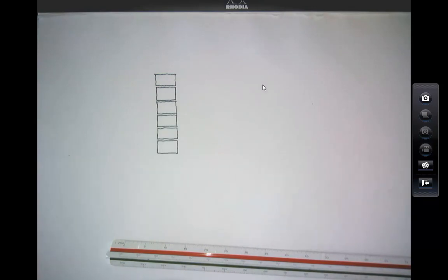So what we do nowadays is we build the inner skin from a light steel frame, and we clad it on the outside with what's called cementitious particulate board, or CP board. I'll pass that around, and it's just a compressed board with a lot of cement in it. So it's very robust. You can drill it. It's not affected by water particularly. So we use that on the outside, and on the inside we'll typically be using plasterboard.